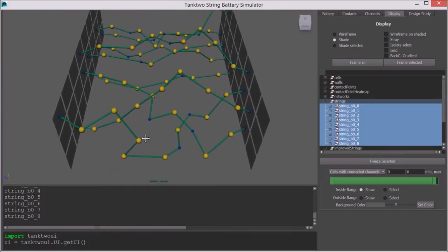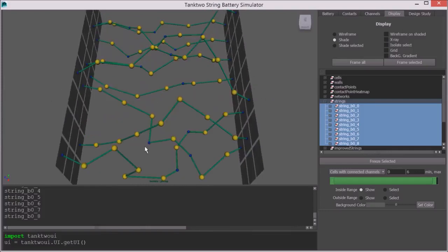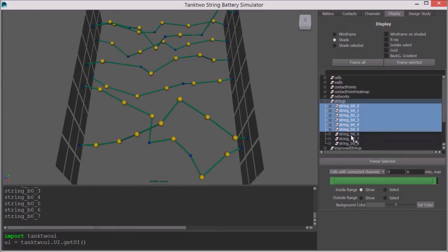Now we have just a bunch of series connected cell strings, which can be combined with the aid of voltage converters. The problem remaining here is that the maximum output power would be rather limited here, because only maybe half of the cells are utilized.